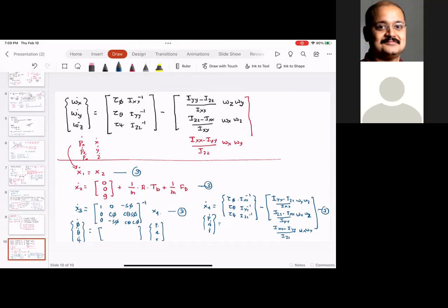Now what happens to the control? For that, I want you to think about where we have control. We have control only of motor speeds. Which means by changing the speeds omega 1, omega 2, omega 3, omega 4, we can manipulate TB. We can manipulate TC, T psi, and T theta. Do you agree with me? That is the control that we have.